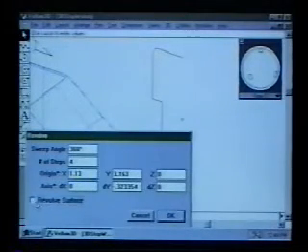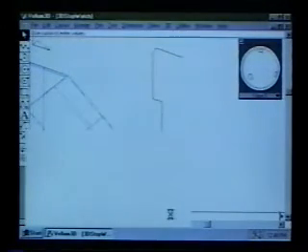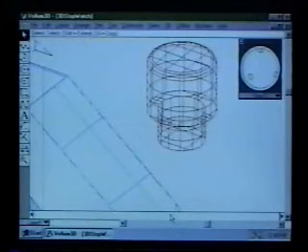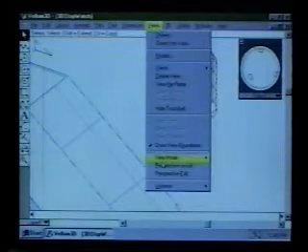And then I check this box here that says revolve surface. And not only will it revolve these items, but it will also put a surface on the revolved shape as well. So it auto surfaces at the same time as doing the revolve. And there's a revolved object, which we can then go ahead and say, view all of this as shaded, if we wanted to, and we could just investigate this and check it out as a shaded form.